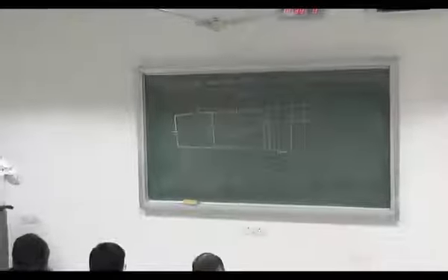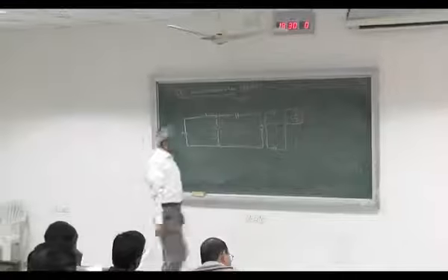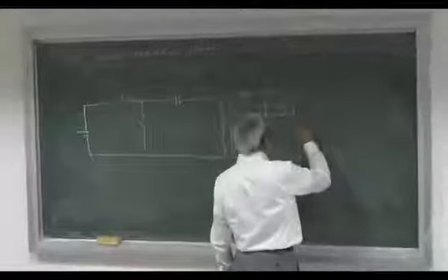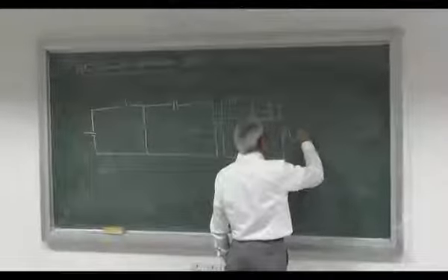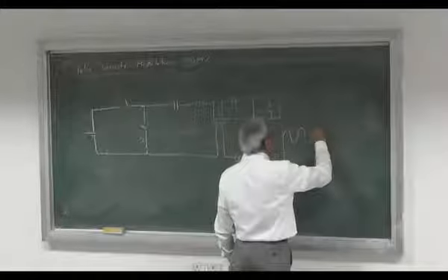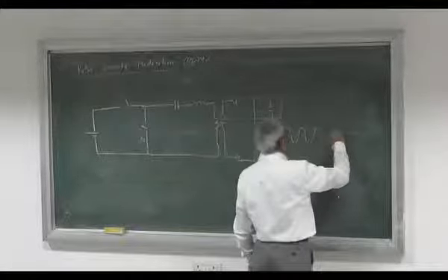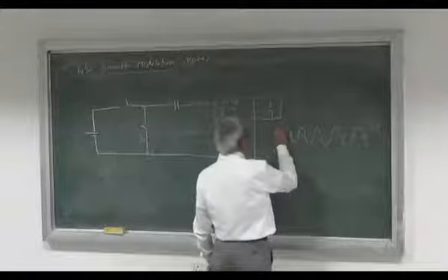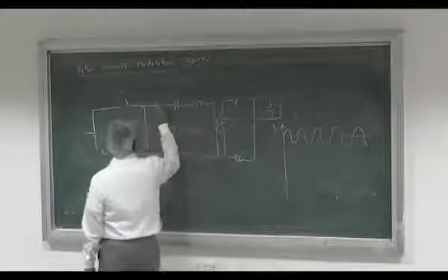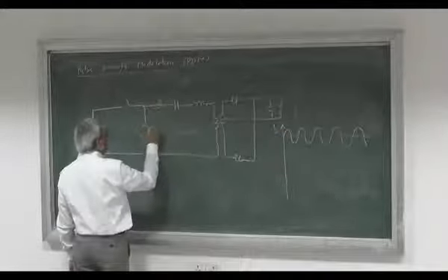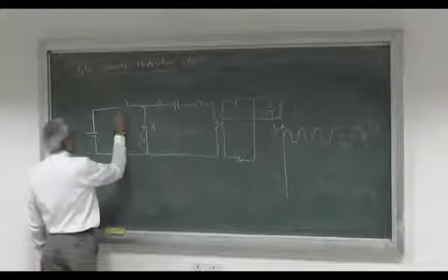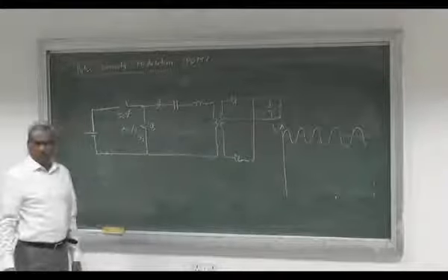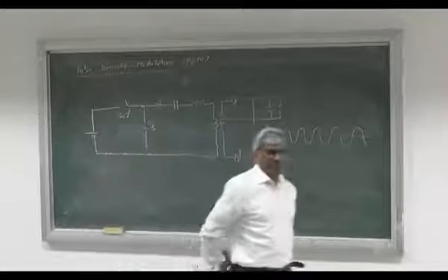So what is pulse density modulation? Let us say we produce this is the current IS we are producing here, and this is VS, and we are operating at 50% duty cycle for the core switching. And we are very close to the resonant point.